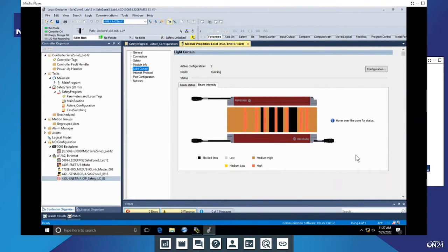So Daniel, if you take your hand out, and now I'm going to demonstrate a classic situation that we all have. Hey, maintenance manager, my light curtains are tripping. I don't know what's going on. This is when we all hit our heads. Daniel is going to demonstrate to us beam intensity changing. All right. So I want you to pay close attention to your light curtains. Did you see how those red beams have now become orange? And if we look at our legend over here, it says that red is high intensity, orange is medium intensity.